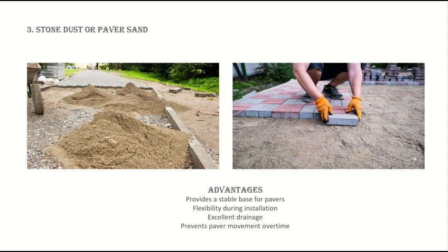As you can see, when we install a paver, we cannot install it just above the gravel because it will not fit perfectly. Even if we install the paver over the plastic base, it's going to slip and it's not going to be as stable as it will be over sand. And also the sand will provide better water seepage, better water absorption, and these things.